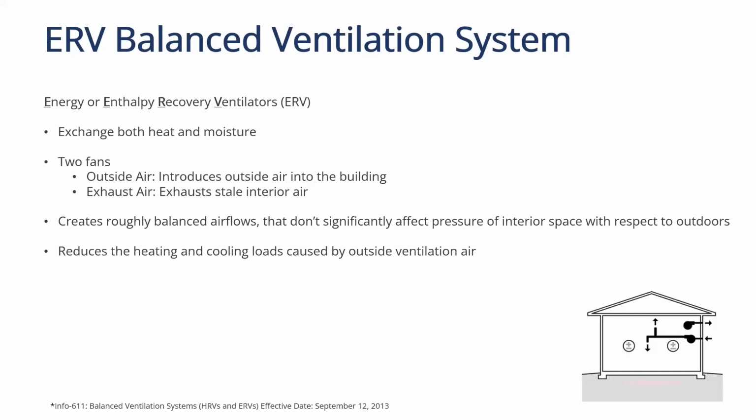And the other big benefit is it reduces the heating and cooling loads caused by that outside air ventilation. Because you're exchanging that air through the ERV, then the unit itself has to do a little less work than it would if you were just bringing in ventilation air on its own.